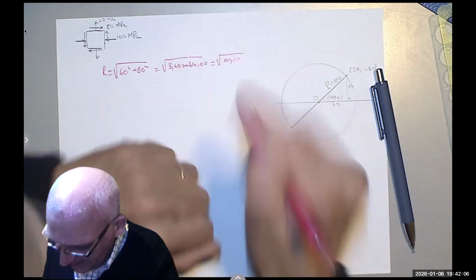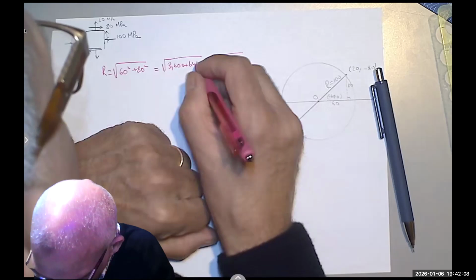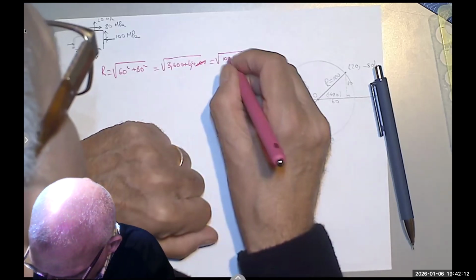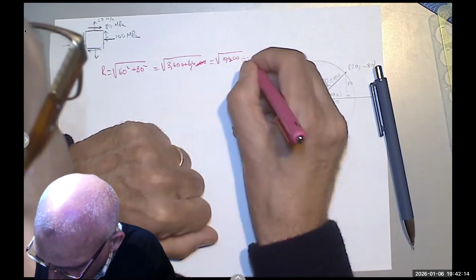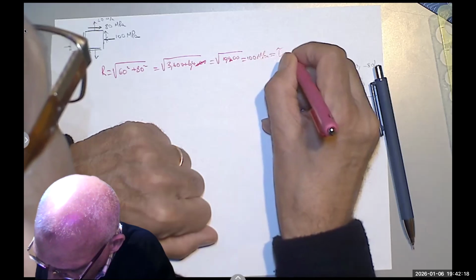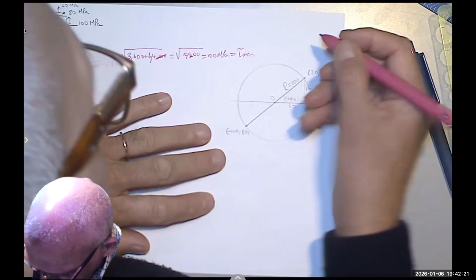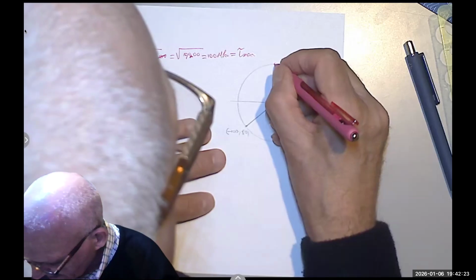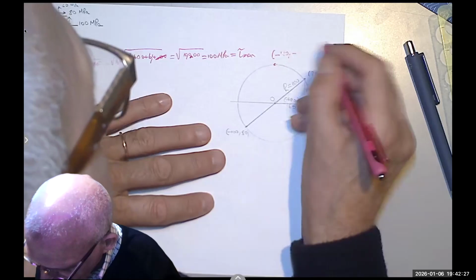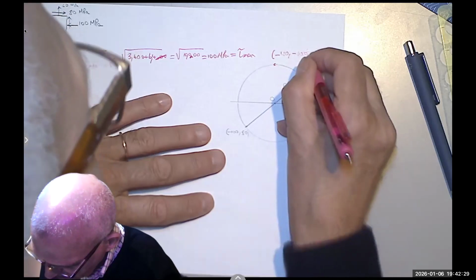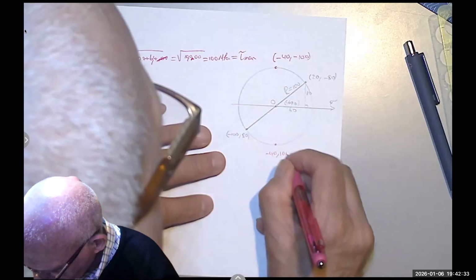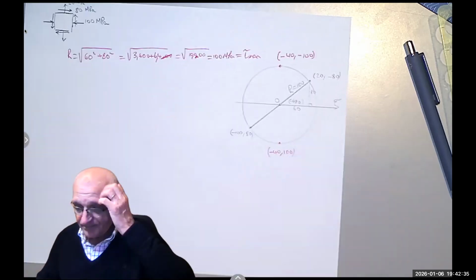which is the square root of 10,000, which is 100 megapascal. That's tau max. Meaning right away, you see, it doesn't take me any time to find out this. This would be negative 40 and negative 100. And this would be negative 40 and positive 100 megapascal.